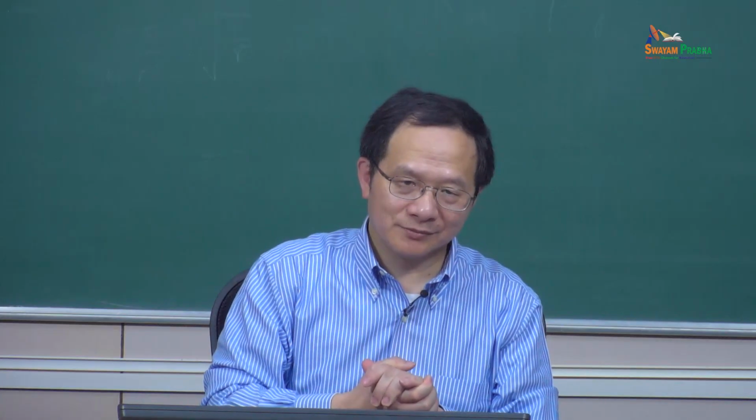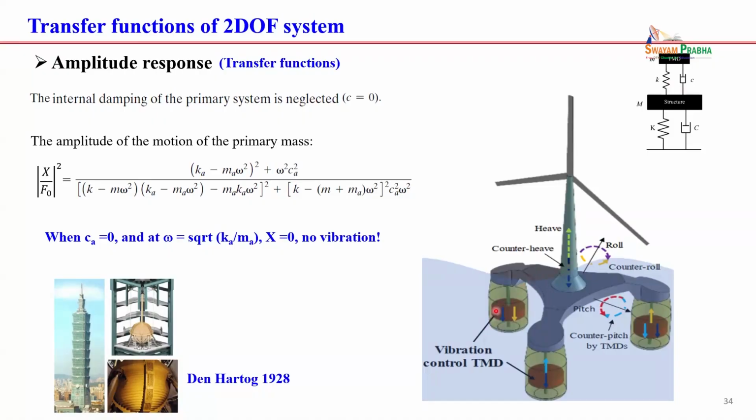We harvest energy from ocean waves. Meanwhile, it acts as a tuned inertial damper. We reduce the vibration. And let me tell you how the tuned inertial damper works. So you have this moving up and down, this drives a ball screw, right? The ball screw drives a generator.